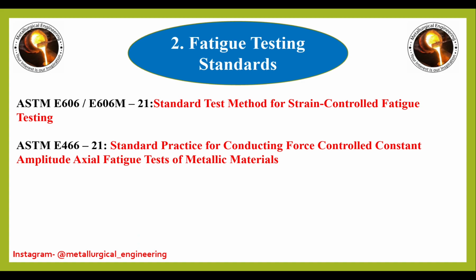Now we'll come to the ASTM standards, first of all for fatigue loading. Here we can see there are different ASTM standards for strain control loading and force control loading. First, ASTM E606 is for strain control, and ASTM E466 is for force control. Now I'll talk briefly about what strain control is.